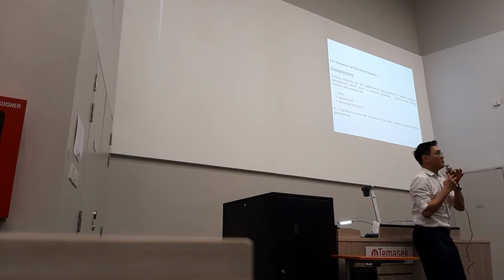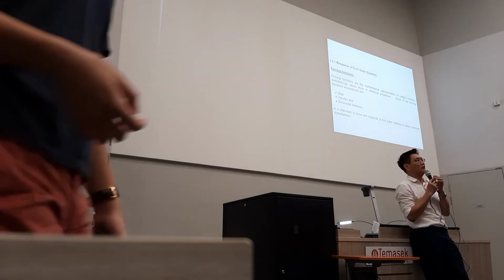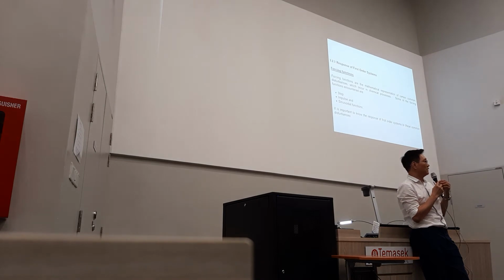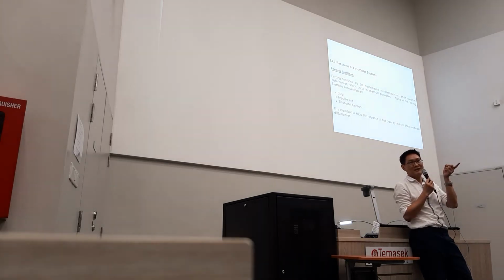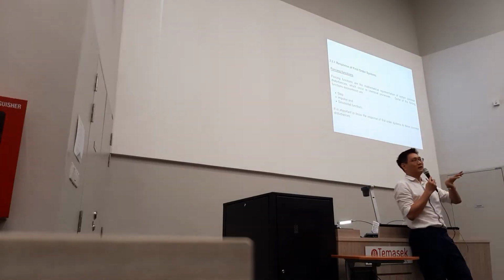Okay, do you still remember what we learned yesterday? I guess most of you are already very good. If I ask you what the formula for the first order transfer function is: Y divided by X equals K divided by tau s plus 1, right? What is Y? Output. The top one is the output, and the X at the bottom is the input.